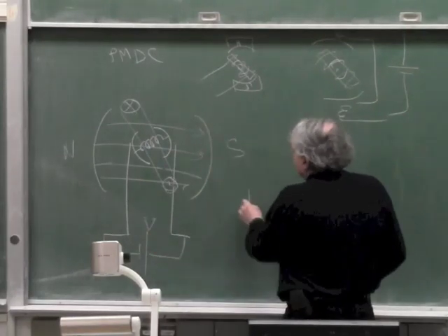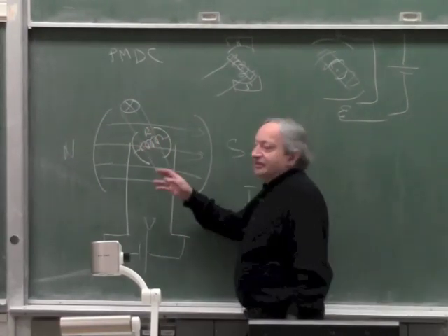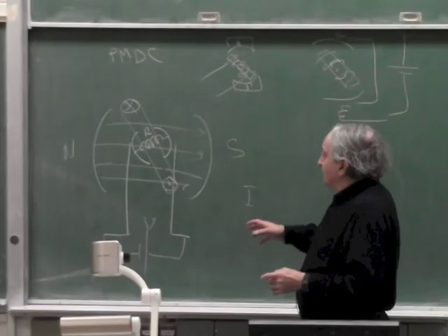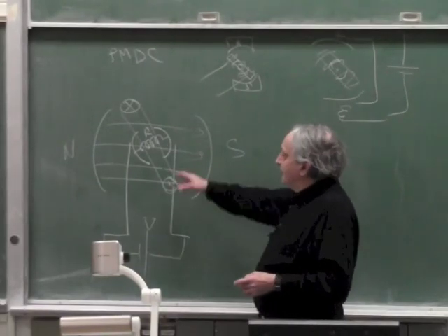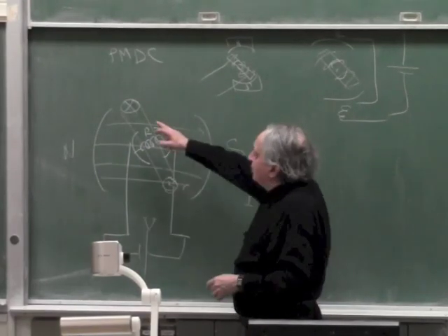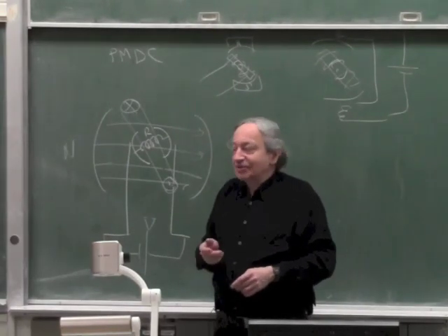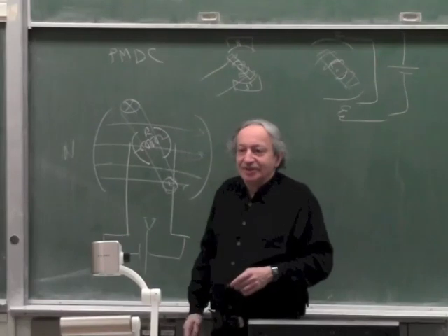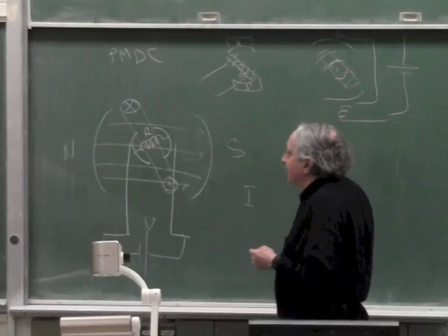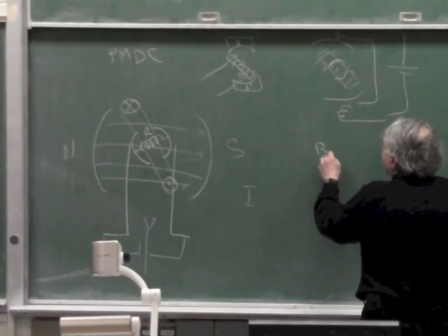So the current is not simply V divided by R. If the motor was stationary, in other words, if I jam it, with a connected battery, the current will simply be V over R. But the moment the motor rotates, each conductor acts as a generator, okay? Because the conductor is cutting through a magnetic field. So the conductor itself, by moving in the magnetic field, generates a reverse voltage, and this reverse voltage is called back EMF in motors.